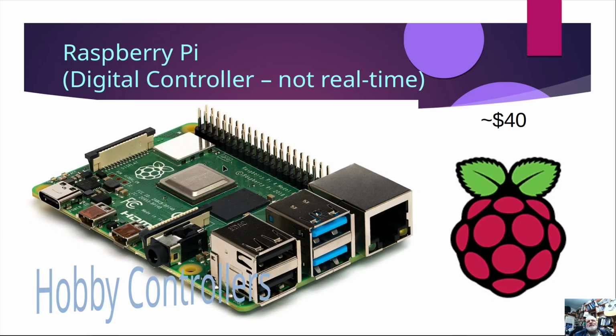So this is a picture of the Raspberry Pi. This one here is the Raspberry Pi 4. It actually has dual HDMI. These are micro HDMI connectors on here, so it can actually run dual monitors. It has a built-in NIC. It doesn't have a built-in Wi-Fi, but it does have USB ports, so you could add a Wi-Fi dongle connection. It has a board here for a camera, and then it has I/O connections over here.